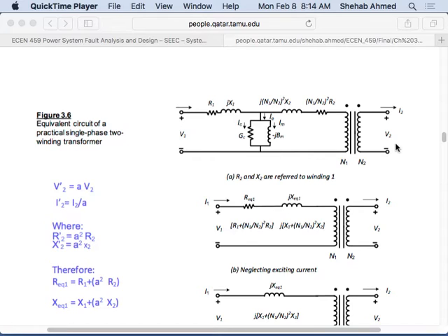When I was working at Schlumberger designing downhole tools, people don't manufacture switches for Schlumberger. They manufacture switches for the market. So you buy electronics used in the market, but instead of running it at 100 amps, we run it at half an amp. We run it at half an amp, and we try to put the best heat sinking available, put the best thermal grease, and make sure that we couple the board to the outside, and we do as much as we can to make sure that we dissipate the heat.